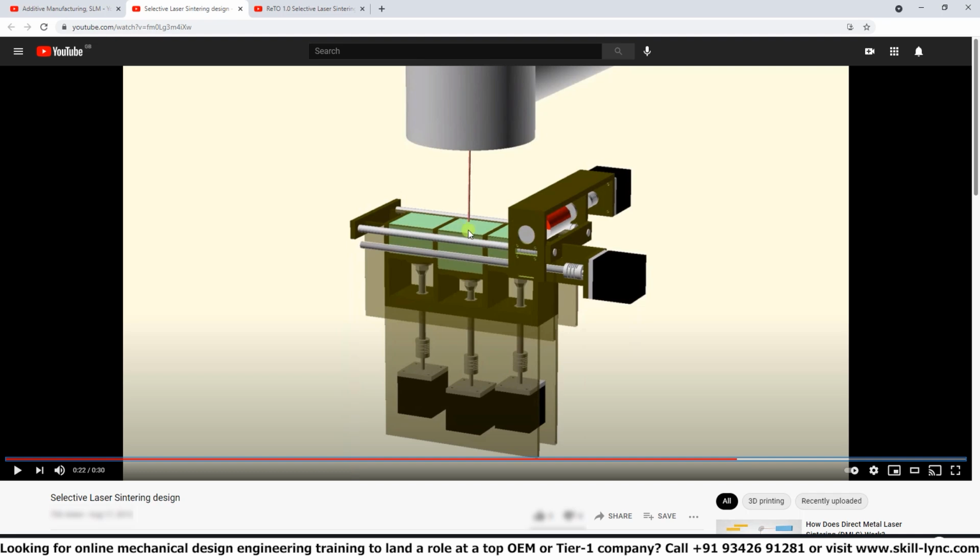I believe there could also be some thermoplastic powders available, but the main use of these machines, because they're so expensive, is with metal, because most of the other 3D printing technologies, as we've discussed, cannot process metal. So it would be a bit of a waste to use such machinery to produce parts from thermoplastic, considering the other much cheaper alternatives that can do that.